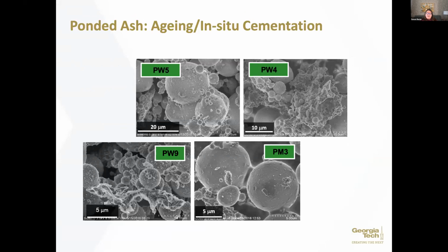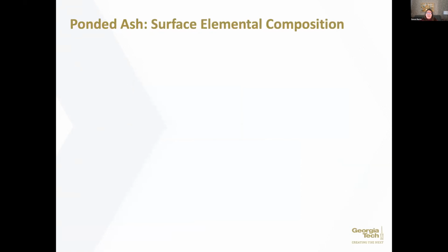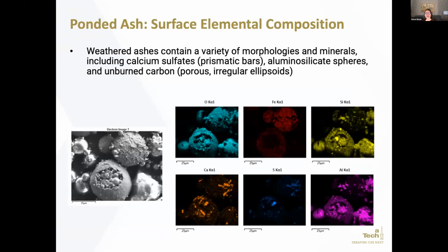What I want you to notice here, the reason why I bring this picture back up, is that these surface coatings on these ashes involve other mineral phases that have precipitated in place. And what we see when we've tested these ashes is a large quantity of hydrated mineral phases present in the ashes themselves. That's going to be important for us when we think about reuse in concrete.